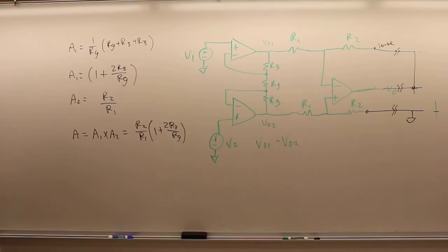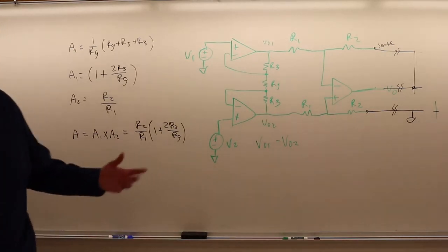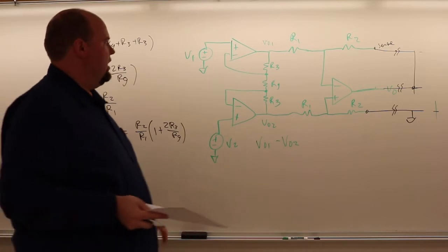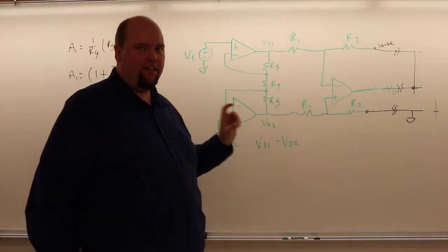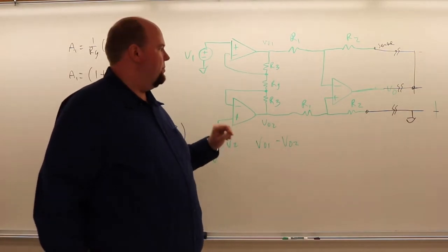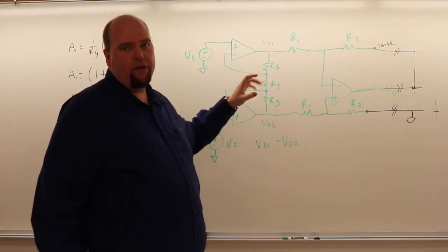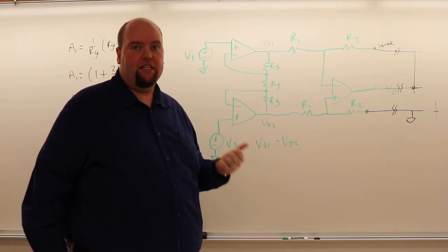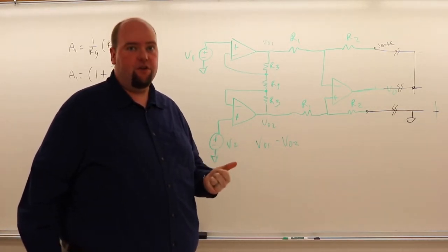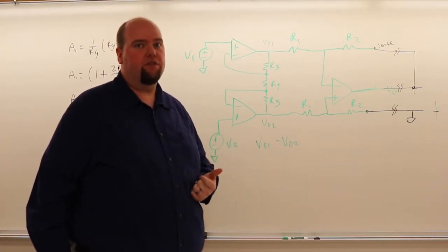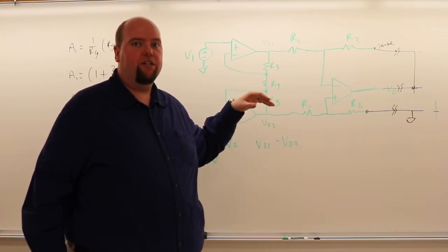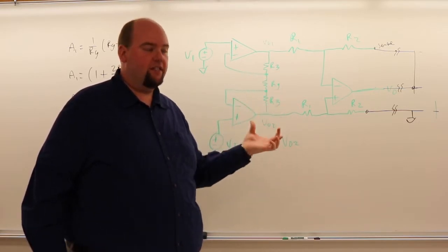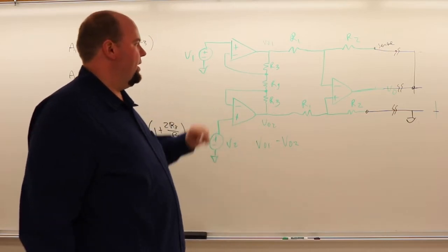As we've already talked about also, one of the main uses of this type of amplifier is that quite often it's easy for us to have a signal represented as a differential value, but that signal will be riding on top of noise, either because of the design of a particular transducer that we're using. So a lot of transducers use a bridge configuration where any amount of noise that's coming on the voltage supply of that bridge will create a differential noise in the signal. So that's one benefit of this.